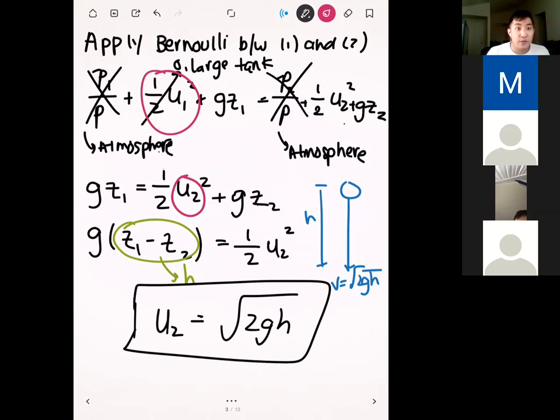The way that you get more velocity in a flow is, by work energy or conservation of energy, you have to perform some kind of work on the flow. Work can come in two different forms for fluids. It can come from pressure forces, which force your fluid forward, or it can come from gravity. If your flow is going from a high place to a low place, then gravity is doing work on your flow. By doing work, you're inputting energy into the flow, and by conservation of energy, that gives it more kinetic energy and more overall energy. Does that make more sense?